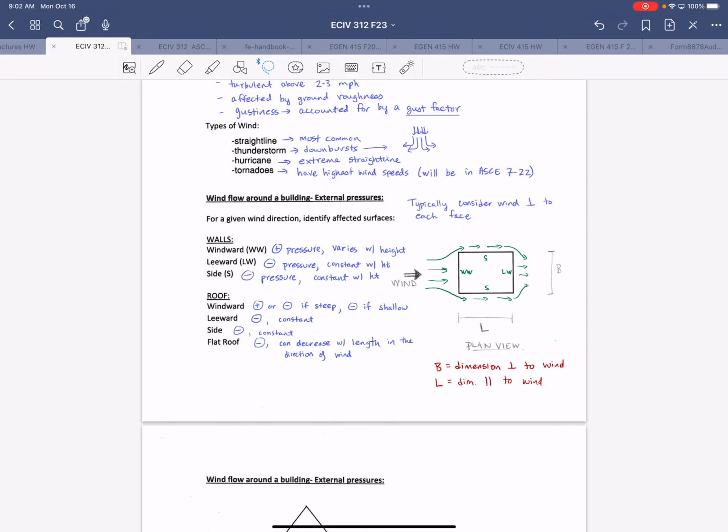So I was looking a lot for, did you follow instructions with the views and the things that were asked for to be provided in each view? There were very specific instructions, and I was kind of picky about that. And then also properly modeling the truss. So that's, again, something that is tied to changing some of the default settings, right?